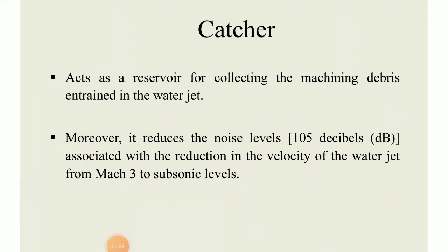Now coming towards the catcher. The catcher is nothing but a reservoir. When the cutting is happening, the workpiece is usually kept on the fixture, wherein the stream of water jet will cut or perform a drilling operation, but after cutting or drilling, it should strike at the bottom section of the tank or the catcher.